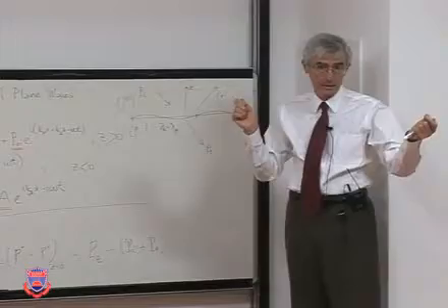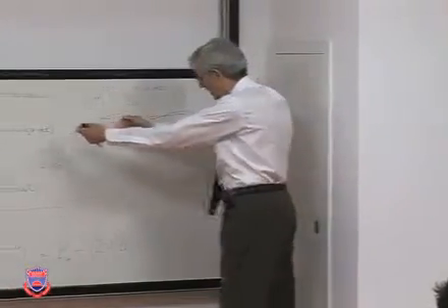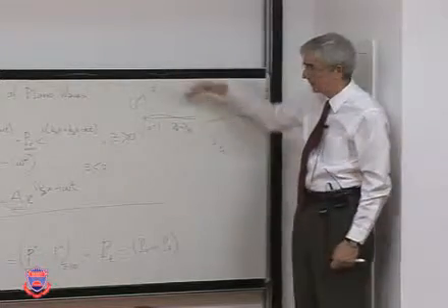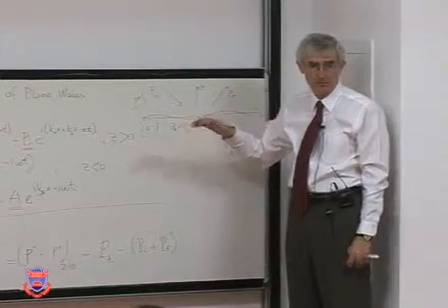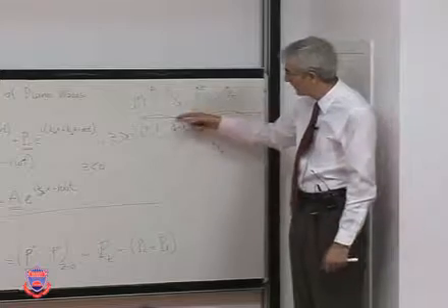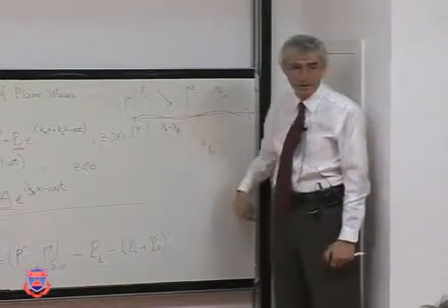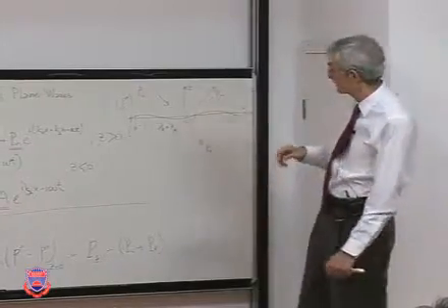That's all the plate sees. This wave that's now a bending wave is traveling on it as a result of this incident wave. Plate doesn't know anything else. Because of that, it radiates out and it radiates to the other side, which is the transmitted sound.